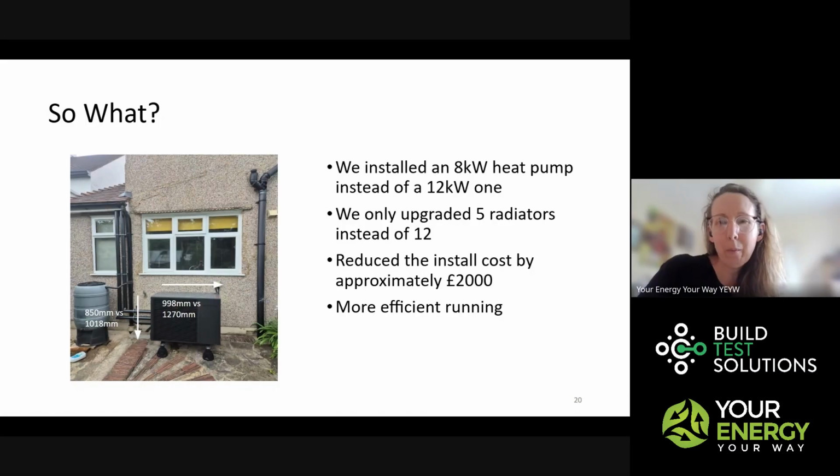that's probably cheating a little bit because it was designed to run at 21 and it's actually running at about 17. So I found the coldest winter day that we had this year, and typically the heat pump flow temperature was somewhere around the 40-degree mark, which is a really nice, low, efficient heat pump flow temperature. So this particular example is running very efficiently, but that is partly because the customers keep their house quite cool.